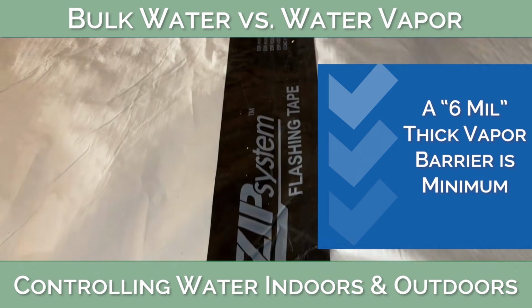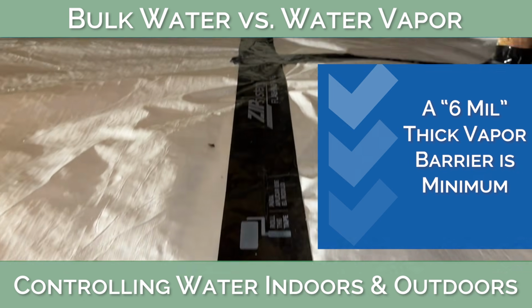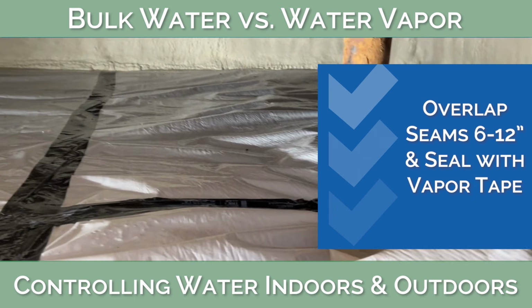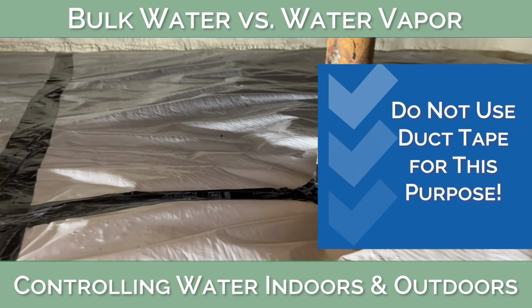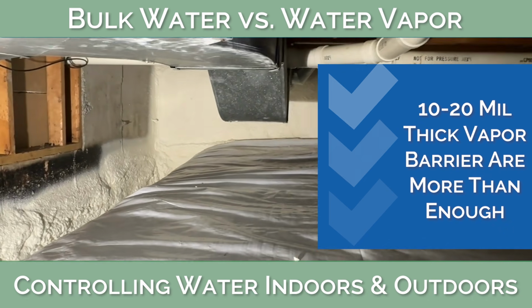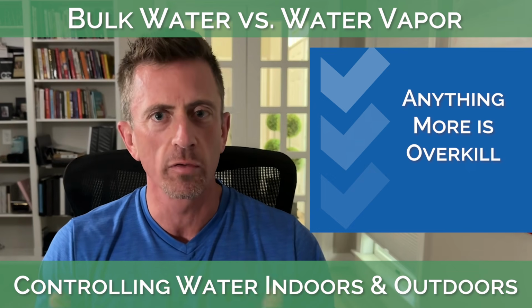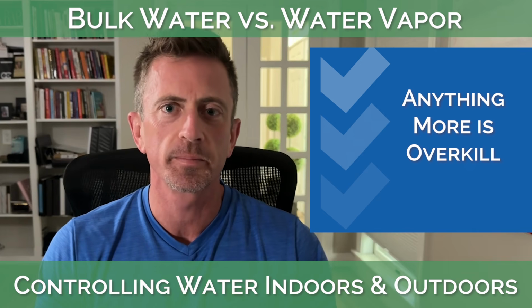A 6 mil thick vapor barrier is the minimum thickness you need over the ground, and the seams should be overlapped 6 to 12 inches and taped with a vapor barrier tape, not duct tape. 10 to 20 mil thick vapor barriers are more than enough for the vast majority of homes, and anything more than that is overkill and likely overpriced.